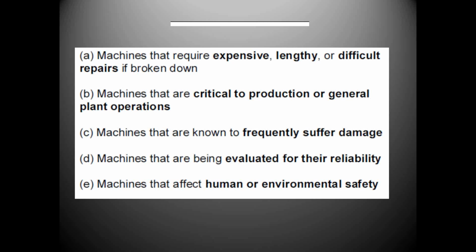So what this gets down to, and we talked about this, I do this with a lot of companies when we do asset criticality. All of your top 10 or 20% of critical equipment, we should be checking vibration on a regular basis or getting it balanced to some real low balance level. And what it does, it lengthens the amount of time that component's going to last. It increases that component's life cycle. So balance is critical in equipment life.